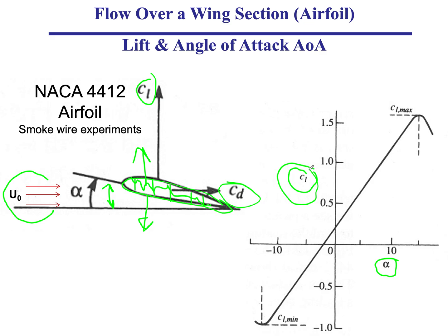So we can conclude from these plots that we have looked at so far that we've always plotted one non-dimensional number against another non-dimensional number, and maybe we have multiple curves for a roughness effect or some other factor. So dimensionless numbers help us describe flows better, and I think the power of it is that it generalizes our results and extends it to experiments well beyond the ones that we have particularly done.